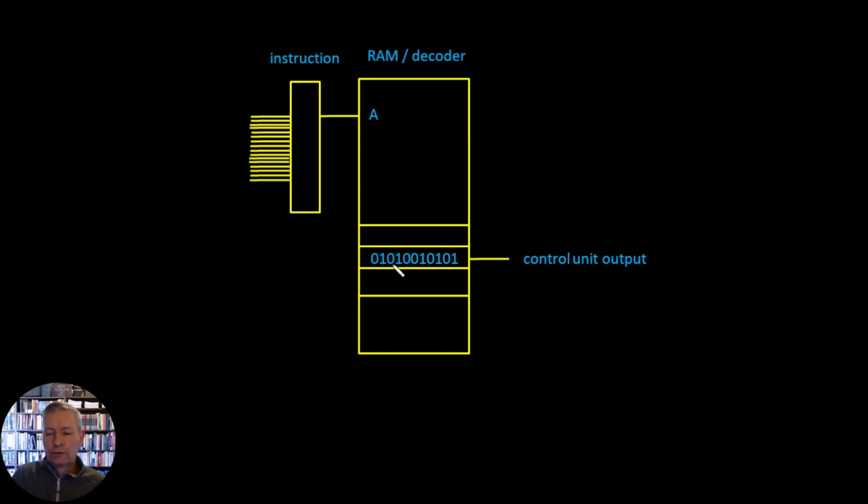But what we want to do is see if we can find a happy balance where we have a part hardwired control unit and part microcoded. This would mean that the wiring becomes a lot simpler, but it doesn't completely disappear. And it means that the generation of the actual codes for our microcoded control unit becomes a lot simpler, and there's a lot less of them. So in effect you get a nice happy medium, and you get the best of both worlds. That's what we want to aim for whenever we change the control unit.